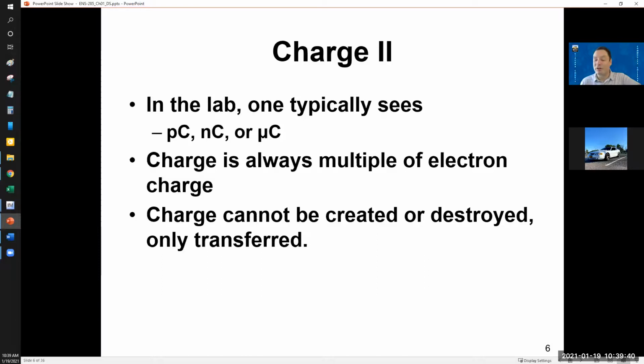And that's actually what we used to use for a capacitor to determine how good our capacitors were, right? You would charge up your capacitor and you look and see, okay, what's the charge after a certain amount of time? And capacitors have what's called a leakage rate, right? So they lose charge over time. You know, some capacitors are better than others. Your computer memory, DRAM, needs to be refreshed because the capacitors lose charge.